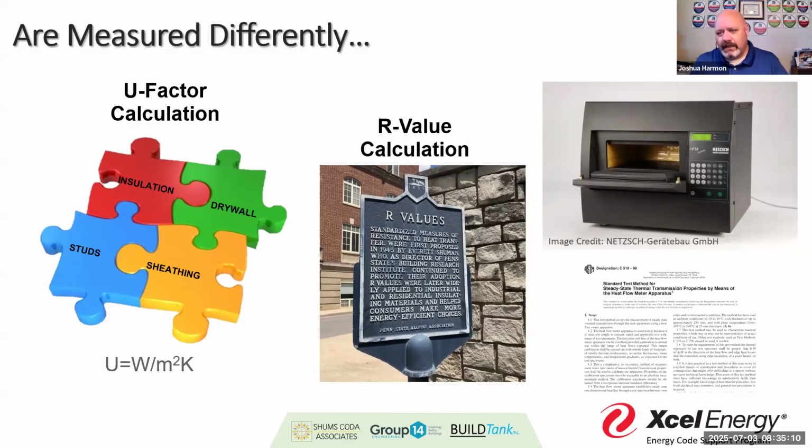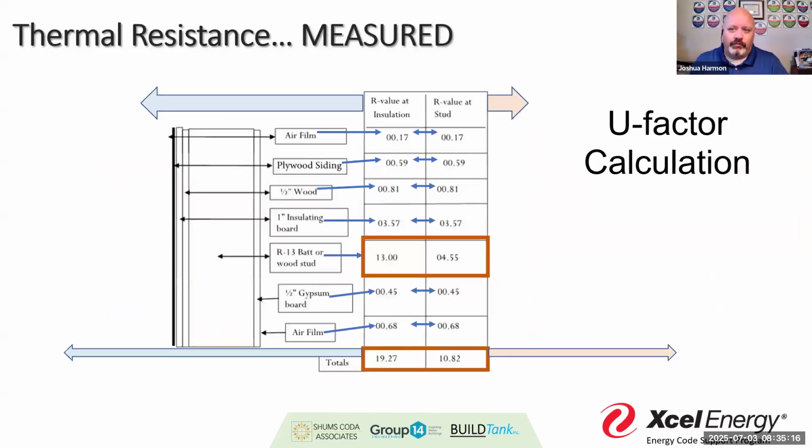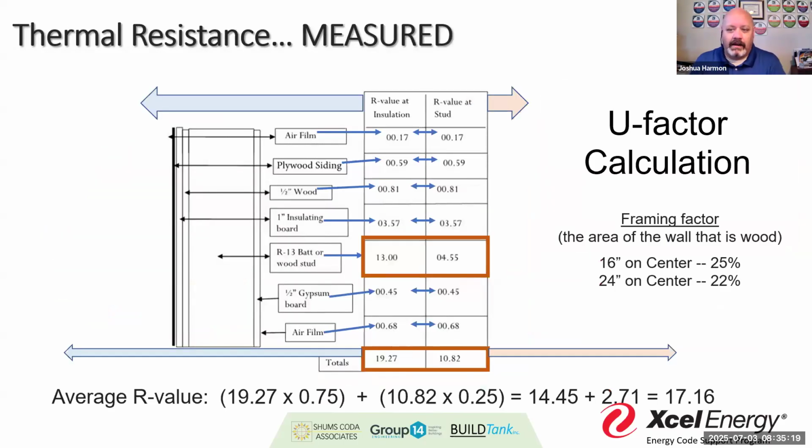So again, there are different methods to measure that thermal envelope, and so it's important for us to think about how those buildings are built, and how much of that wall is there versus other components. This is something that changes a lot when we start talking about different designs, whether we're using a wood frame, or in most commercial we're using steel or metal framing, and so then we're going to have different thermal bridging impacts that may come into play.